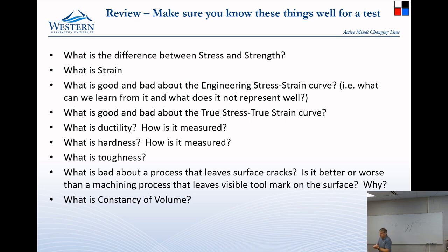I wrote surface defects reduce the ductility of materials. Okay, so they reduce the ductility, it will fracture at a lower strength, or a lower amount of strain. So it is bad in tensile loading. It doesn't matter much in compressive loading, but if that area is loaded in tension, then it has the opportunity for that crack to propagate, and it's really bad in oscillating conditions.